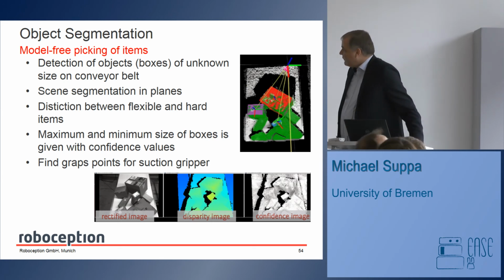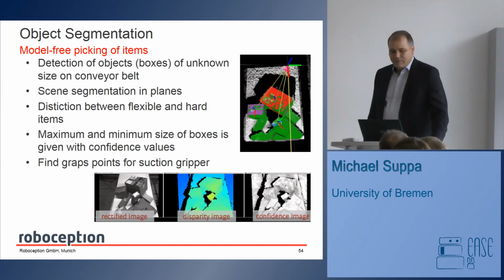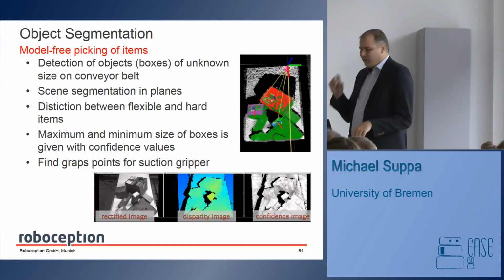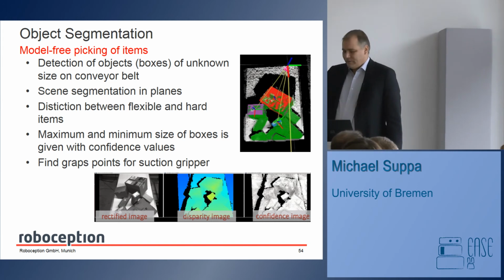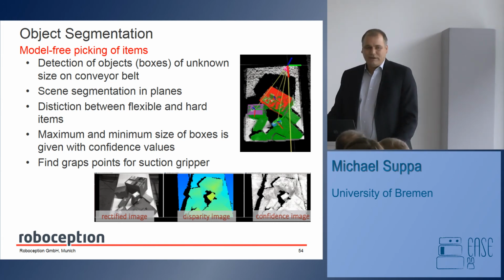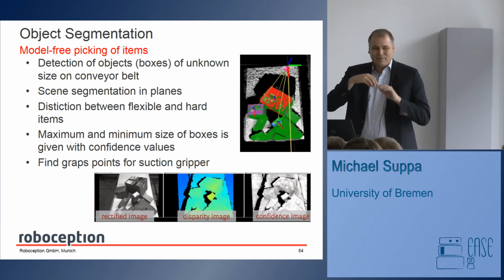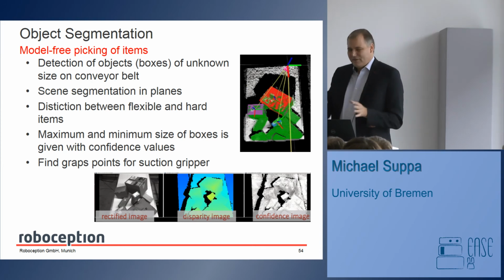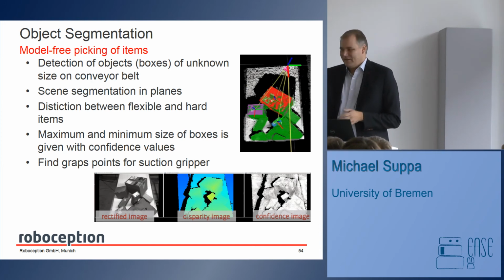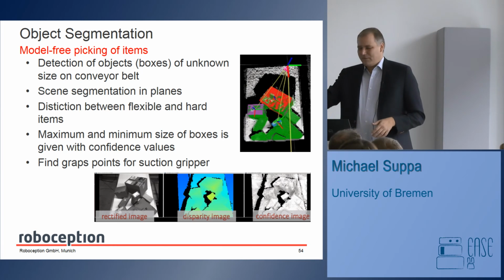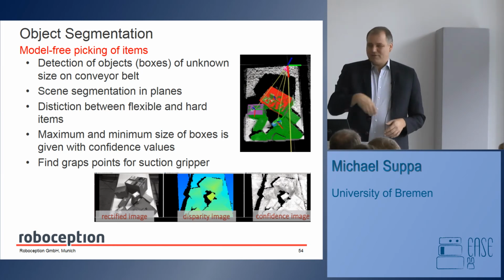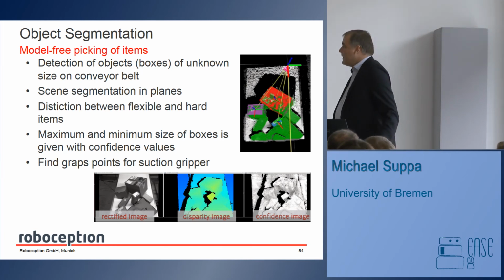So what we designed for that is a very simple segmentation approach. You don't go for a two-finger gripper. A two-finger gripper, positioning it, grasping something out, is way too slow. The simplest way is to have a suction cup, suck it from the top, and drop it to the next one. You don't think about placement. It's not really necessary to accurately grasp the piece. Just take it out. The human's the same. If you have it a little bit to the left, just throw it in the bin. That's what you have to do.